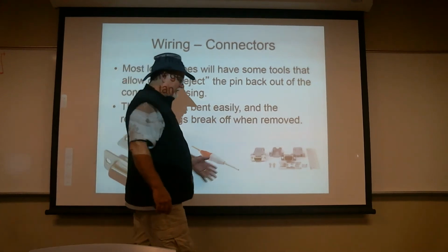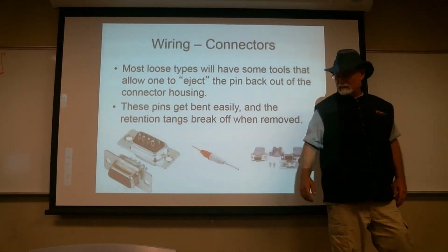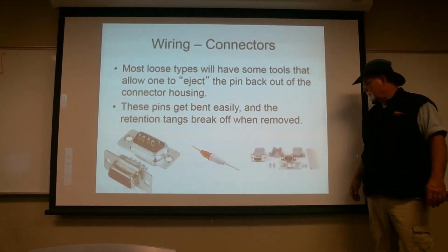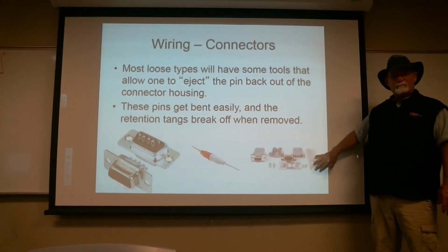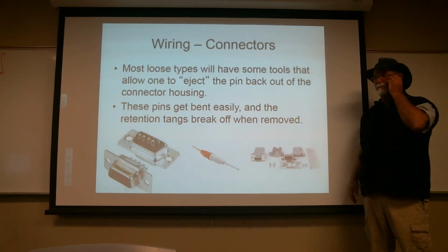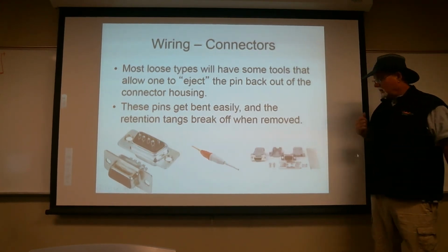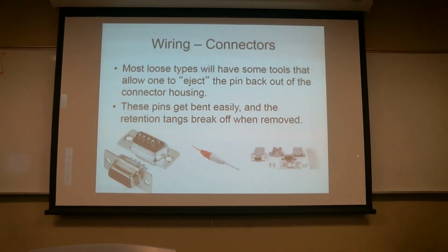This is sort of the same thing, RS-232. I think that's like a 15 pin or something. But this shows the same idea, but now I have separate pins that you crimp on, slide in, and they click into place. The tang, the part that locks it into place, in these types, it's usually actually the housing that has a little lock in.